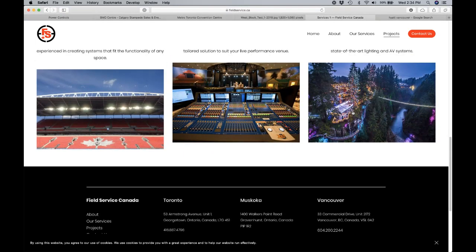And we had to come up with a unique take on dealing with lighting control in this venue. What we ended up actually doing was putting a distributed power control system in the whole venue. We are running with use of the Paradigm system and interfaces and mosaic boxes. We're actually running large high current contactors, and we're turning off 100 amp panel feeds throughout the park, where they're able to turn on whole panels to light up all of the Christmas lights on, say, those 10 150-foot tall trees.